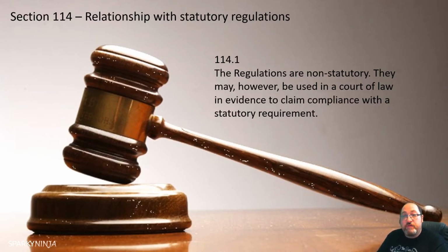So they had a rules procedure created, and they created this line that said that it'd be an isolating transformer, and some of them were allowed an isolating transformer up to the 250 volts, but some were only allowed ELV isolating as well because of extra risks. So they exercised a control over the norm, and we had to follow that.